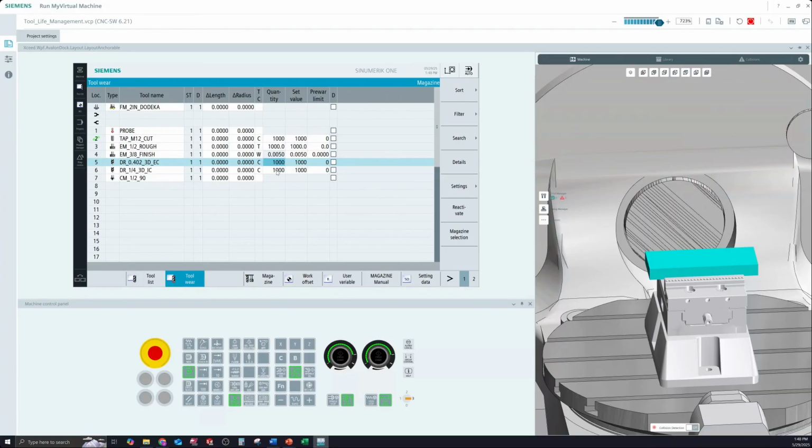Now there's a couple disclaimers here I want to mention. Notice how I'm only doing this on the ones that I have set for time and count. That's because I've only written the macro to account for these two. I did not write it to track wear, because I felt like wear is your judgment call. Maybe somebody has a better example, but the only time I can think of for using wear would be my finishing tools. And at that point, it's a judgment call on you, how much wear you're okay with having before you need to change that out.